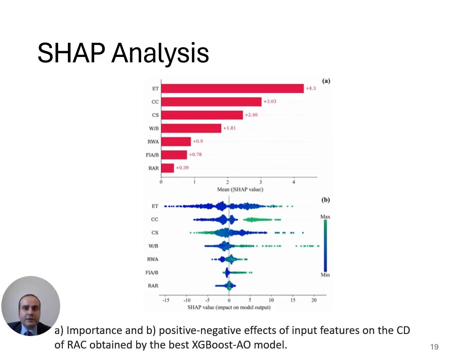This figure illustrates the impact intensity of the selected input features on the carbonation depths of recycled aggregate concrete, as well as their positive or negative influences. In total, environmental factors affect the carbonation depths more critically than recycled aggregate concrete mix design factors. The exposure time, with the mean absolute SHAP value of 4.3, has the first rank, which is a 42% mean absolute SHAP value difference compared to CO2 concentration.